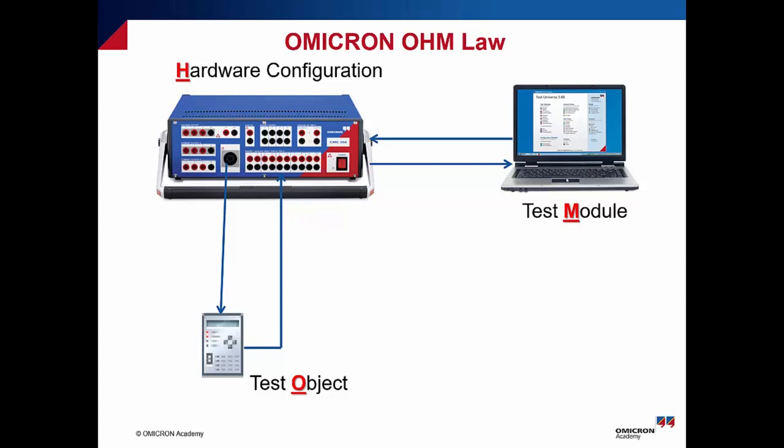Let's give you an example. We have here a differential protection. For this differential protection, for sure, we have to apply differential protection test modules, which is not applicable to use a distance protection, for example, in this application, or overcurrent if we are testing only the differential function.